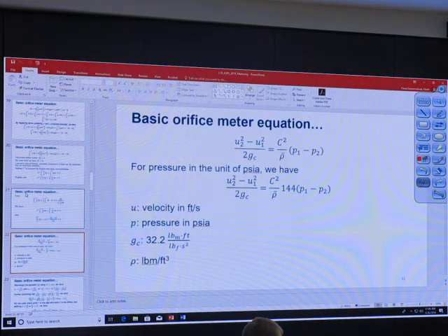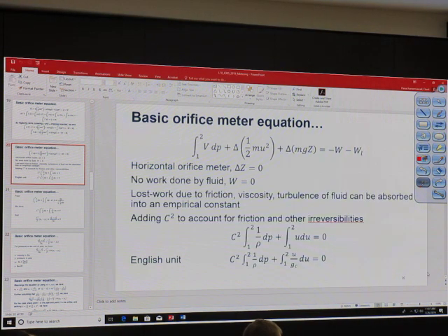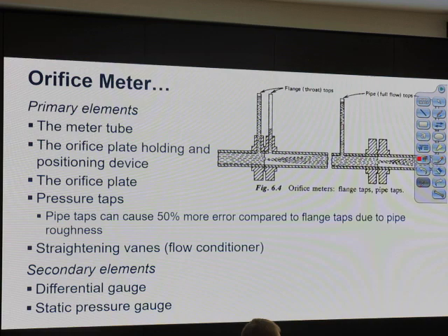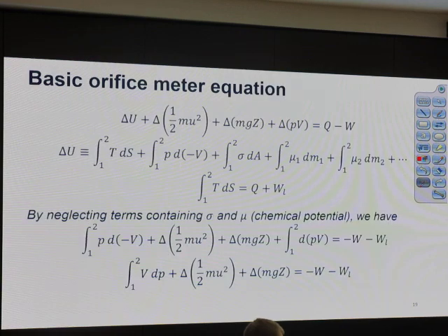Oh yeah. Last time we stopped at the orifice method. Okay, we use the orifice method because it gives us relatively accurate flow rate measurement for gas test. The better meter will be the Coriolis flow meter, but of course the Coriolis flow meter will be more expensive. For this time we will quickly go through the derivation of the orifice plate equation. I don't test you on the derivation, okay? The derivation here is just so you know what the assumptions are. What I can actually test you on is what the assumptions are.